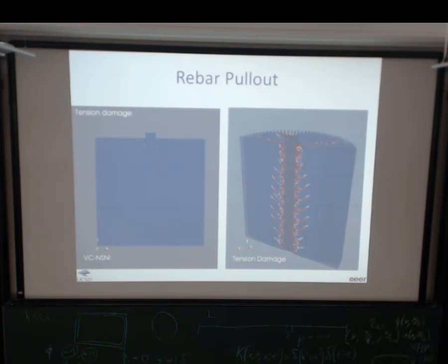Okay, so you can now study this, and we actually use this to construct another damage model. That damage model is for the debonding between reinforcement and the matrix material. Right? So then once you have this, you can use this to do various different things. This is one application, to get the debonding damage model for composite material.